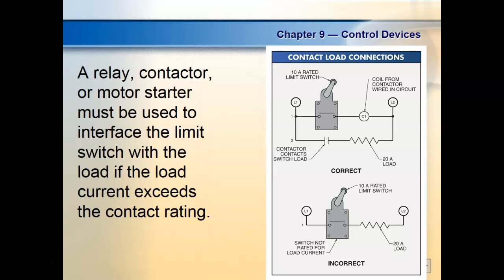So voltage is a push. There's nothing out there in the world that has infinite resistance. So what happens is when we break that push, how much push can that contact break without it arcing over? So your contacts are going to be rated in a voltage, how much you can actually break.